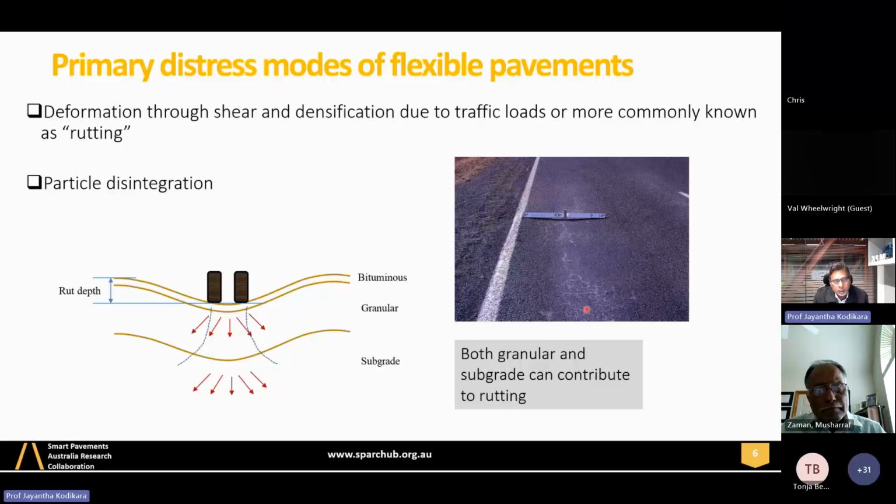Yeah, that's what I suggested. I said we have a lot of problems at the moment with those correlations, and it is hit and miss in many instances. But for asphalt, it's always a miss because of that issue. Temperature is high, therefore density is changing during asphalt compaction, but modulus remains the same. Modulus remains the same because of the softening point and the asphalt is flowing, otherwise you cannot compact, so your ICMV parameters won't change. For asphalt, it's a problem.